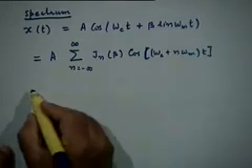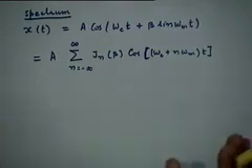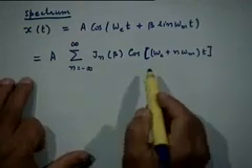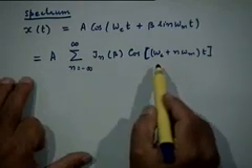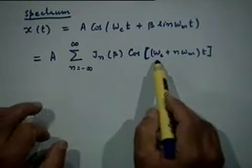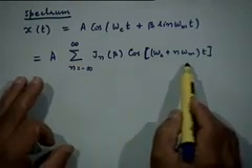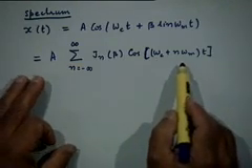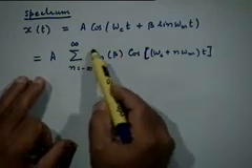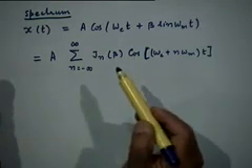So what do we find? First of all, before we discuss any further, of course this is obvious from this expression that we have a very large number of frequency components, unlike the AM case where the frequency components were omega c plus omega m and omega c minus omega m. We have a very large number of spectral components present here, right, and the behavior of the spectrum is dictated by the behavior of these coefficients, which are Bessel function values, right.